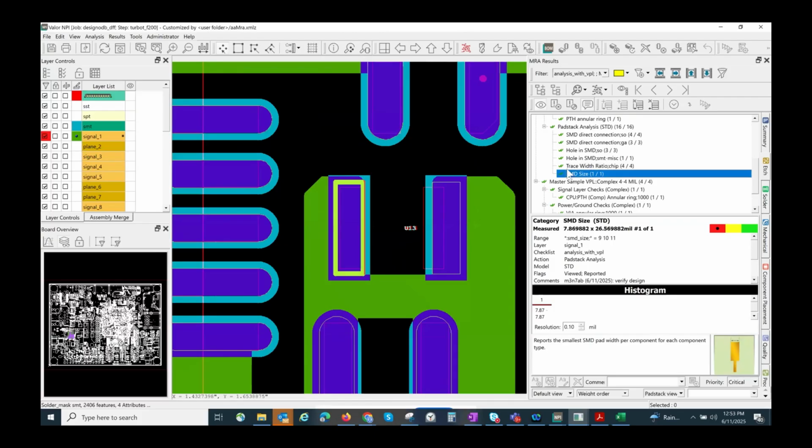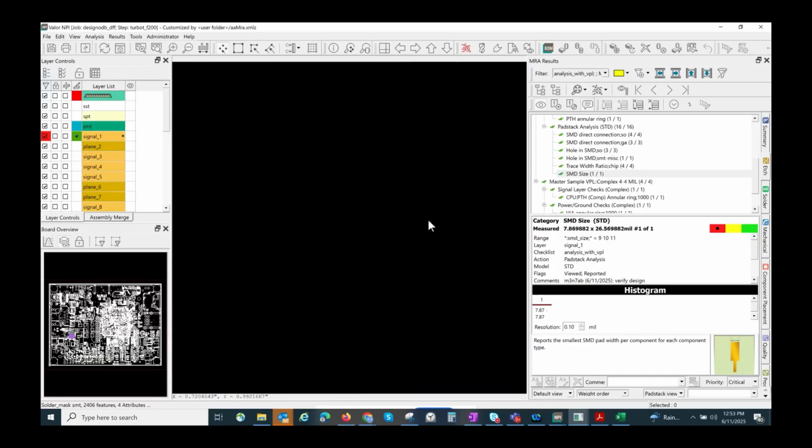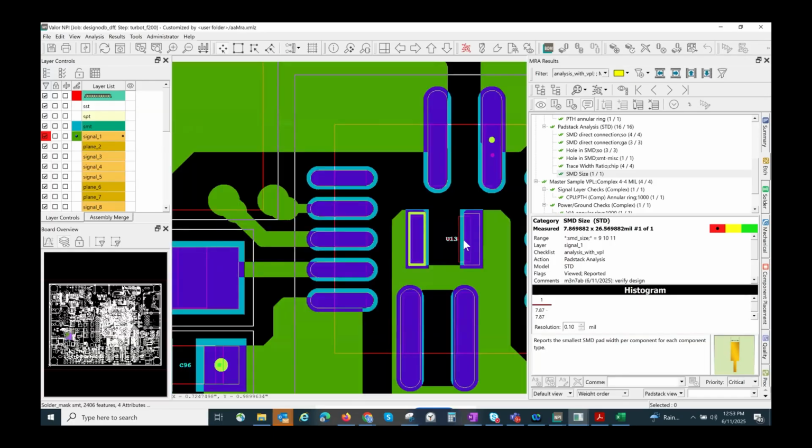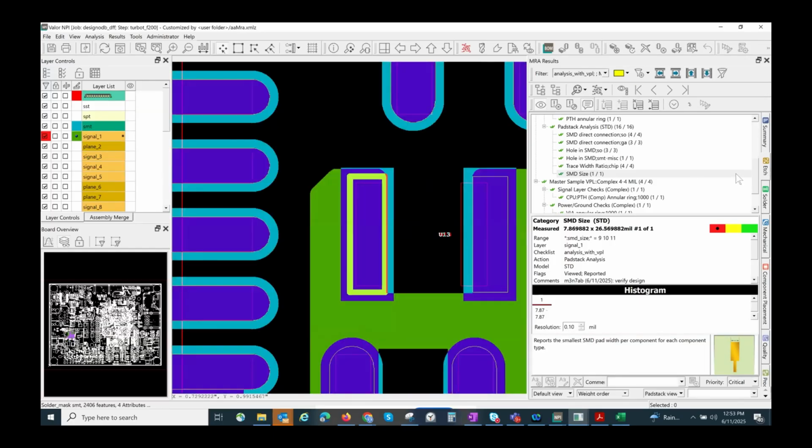We also have a check for making sure that the pad sizes are actually suitable for the components. In this case, it looks like because of the component type actually assigned to this place, it's not going to fit correctly. This is just the edge check, checking the pads, but there's an extended list of checks for the component assembly as well, checking the solder joints, checking the spacing, pin to pad, all that.